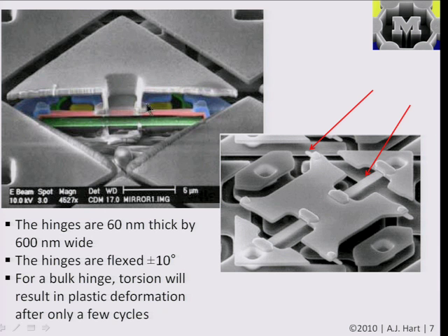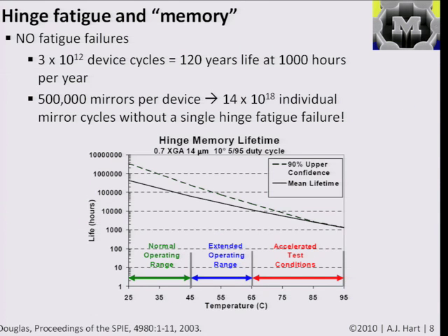But it turns out that, I don't know if it was by accident or by engineered development, but by controlling the deposition of this nickel film and then subsequent annealing of it, they can guarantee that these beams are individual single crystals, meaning they have no grain boundaries and they have a very small number of defects. And because each of these is a single crystal, its properties can approach the ideal value we would expect based on the crystal structure. And this lets them realize devices that have an extraordinary fatigue life.